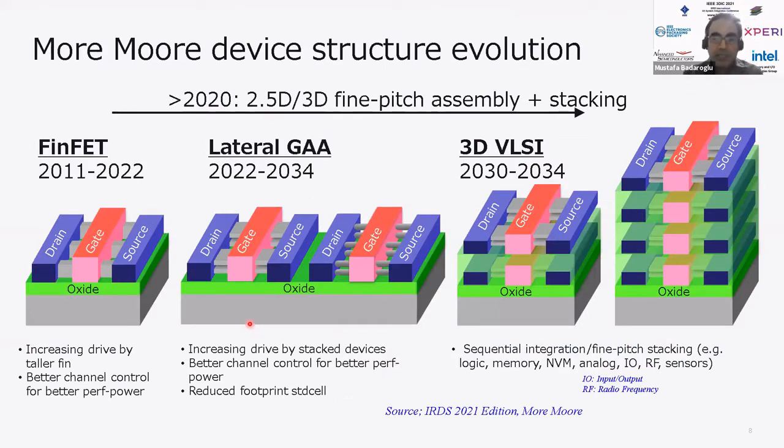So if we look at the other side, the technology capability, from a device structure point of view, we were happily enjoying the FinFET for more than a decade, and it is expected to scale pretty well to the 3 nanometer node, which is actually defined around the second half of 2022. And this is a very effective device because it's also exploiting the 3D direction very well: taller fin, increasing the drive, and also reasonably better low power characteristics due to channel control.